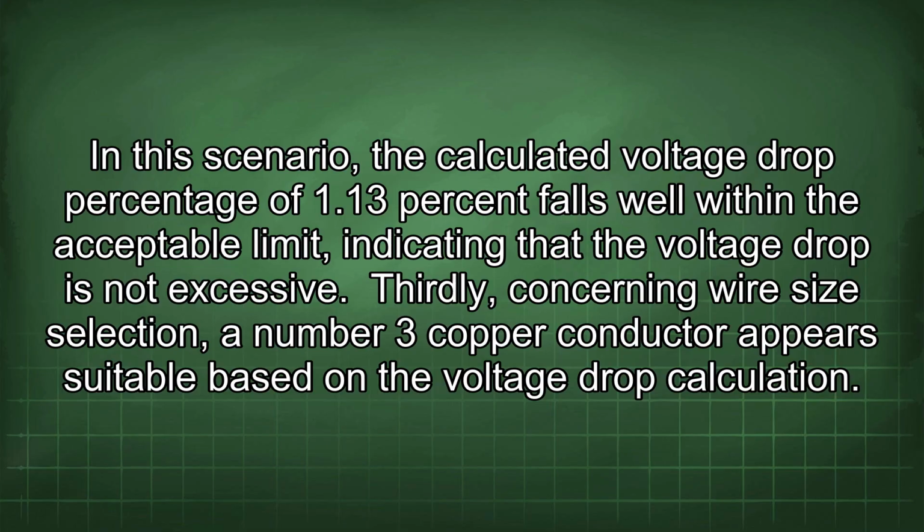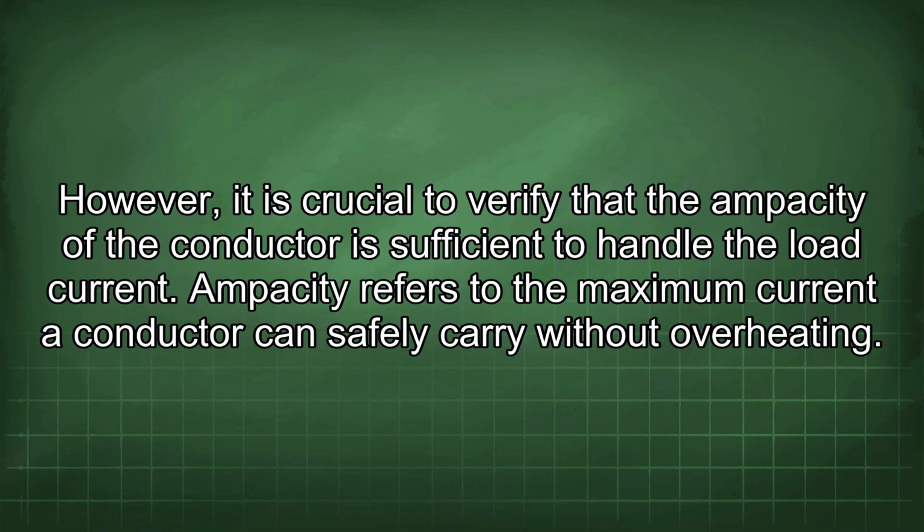Thirdly, concerning wire size selection, a number 3 copper conductor appears suitable based on the voltage drop calculation. However, it is crucial to verify that the ampacity of the conductor is sufficient to handle the load current. Ampacity refers to the maximum current a conductor can safely carry without overheating.